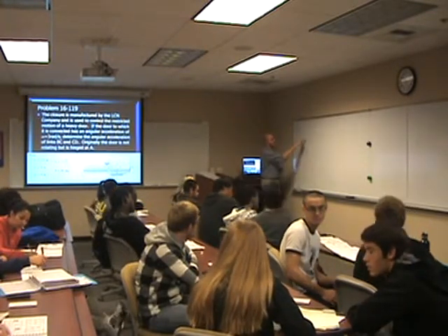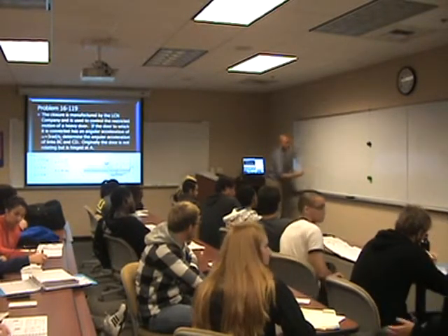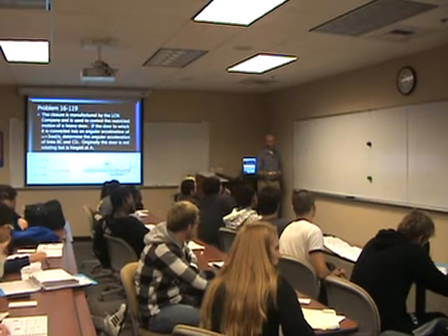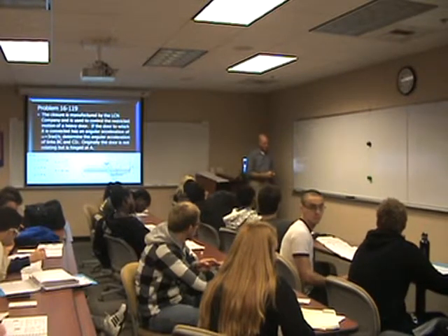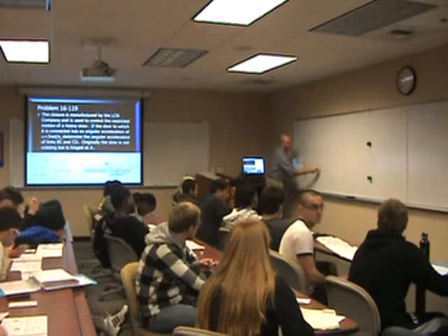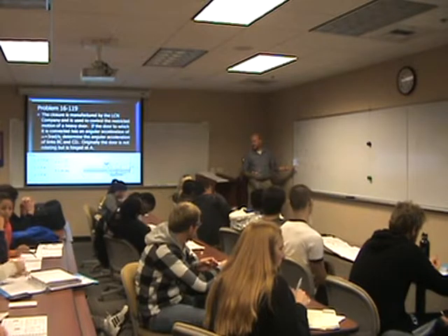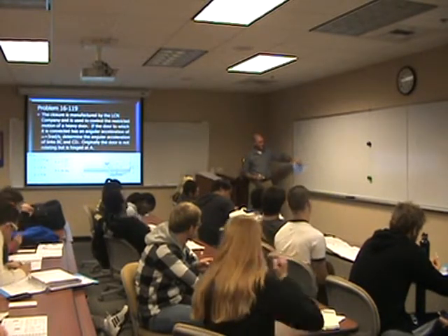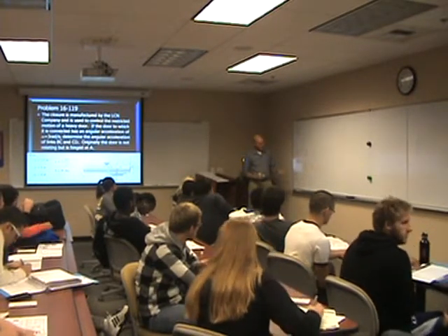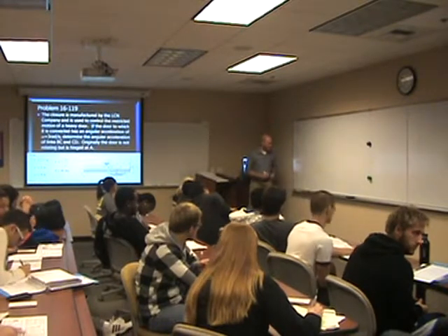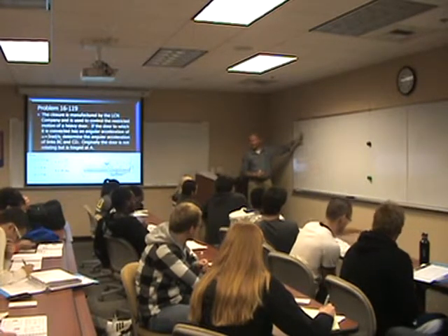So plus R3 times alpha BC, and this is in what direction? This is also to the right. And so this term here is that term there. Once we have it like this, it's a lot easier than trying to figure out what the square root of R1 squared plus R2 squared times alpha is, and then breaking down the sine and cosine. So then we can basically take our equations in the x and the equations in the y and go from there.